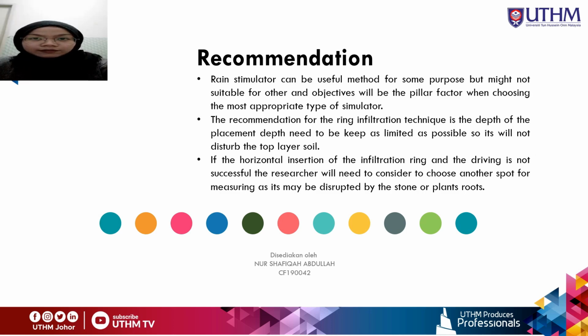For our project review recommendation, the rain simulator can be a useful method for some purposes but might not be suitable for others. The objective of the project will be the factor when choosing the most appropriate type of simulator. For the ring infiltration technique, the placement depth needs to be kept as limited as possible so it will not disturb the top layer of soil. And if the horizontal insertion of the infiltration ring and the driving is not successful, then we will need to choose another spot for measuring, as it may be disrupted by a stone or a plant root.